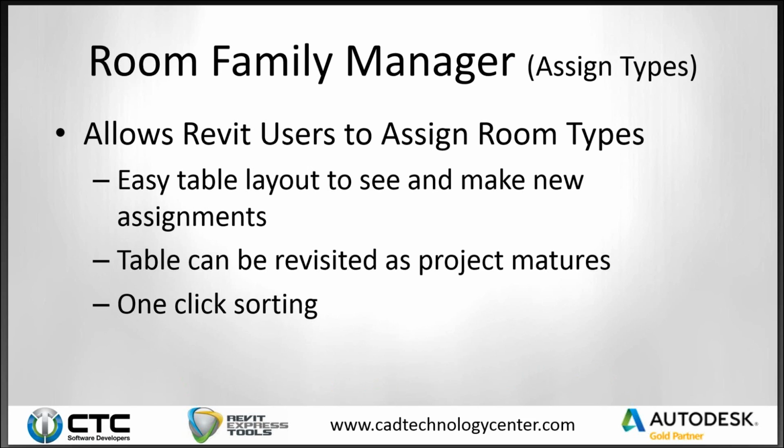Ultimately, you can assign room types to actual drawn rooms in the Revit model. It allows you an easy table to see the actual Revit rooms and to make new assignments. You can always revisit this and reassign room types as time goes on, if need be. And you can also continue to refine it as the project matures and continue to assign room types as rooms are placed. It also allows for some nice little sorting in there so you can easily sort your rooms. And we'll kind of take a look at that today after we refine a couple of rooms in the floor plan view.